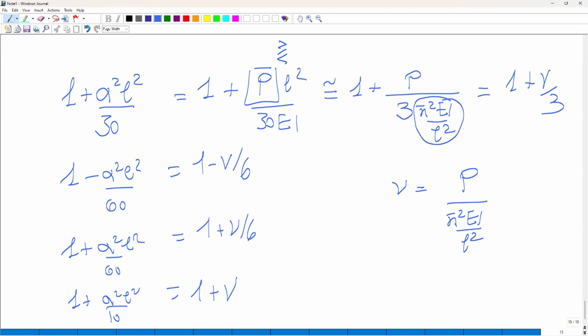So this is also the reason to allow the check engineer to go through your process and check it by sample. So hand calculations you will do as a design engineer, because you have to prove and check the reliability of your computer model, but also as a check engineer, as a final validation engineer, probably you will work with them just to guarantee that. Because in the end, you will say, okay, I certify that what has been built respects the assumptions and so on, and the tests fulfill the design. So it's good to have the sensibility of these numbers.